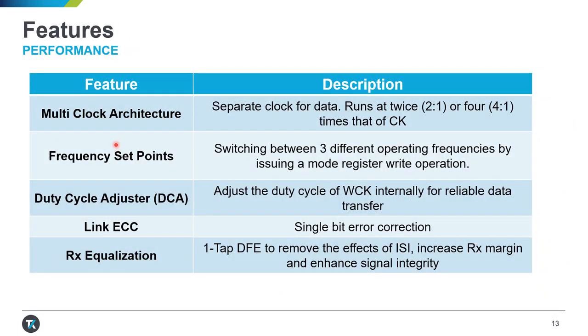In this slide, I quickly want to highlight a few features that improve the performance of LPDDR5 SDRAM. They are multiple clock architecture, which we talked about in detail in previous slides. We have 3 frequency set points as compared to 2 in LP4. We have a duty cycle adjuster and monitor that improves the duty cycle of WCK inside the DRAM. And we also have optional link ECC and one-tap DFE to increase the robustness of the memory channel.